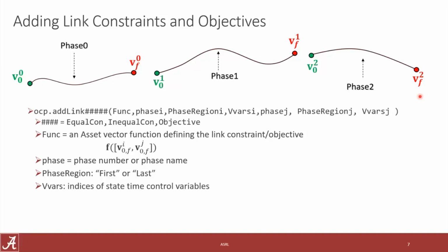Or an example is, as soon as this sail deploys, before that the sail is closed, and then you're changing the dynamics, you're adding a sail in there. Okay, yeah, whereas in a collocation method within one of those segments, it's ensuring that the dynamics you've set up for that problem are feasible throughout the trajectory. Yes. And it continues, but this could be discontinuous, and the dynamics could change.